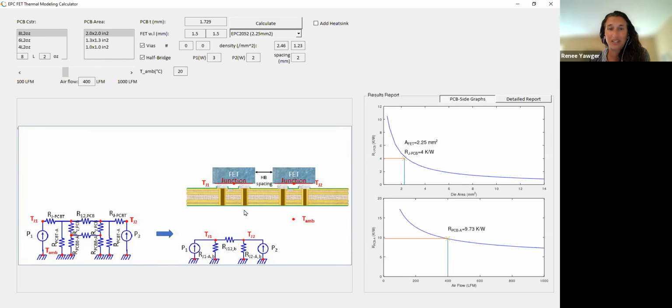So let's see, we have one that says, a practical design question. I have a total loss of 2 watts on a FET and its thermal resistance is 31 degrees C per watt. Do you think the FET can survive without airflow and heat sink? The calculation gives 90 C, but the test shows much higher. Yeah, there's a few things that can account for that,